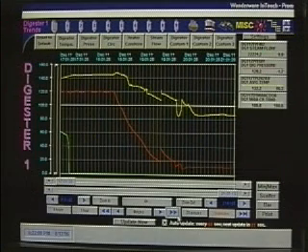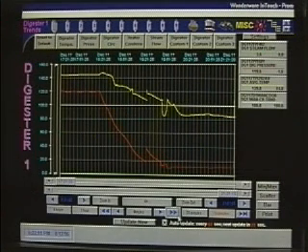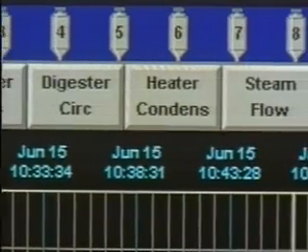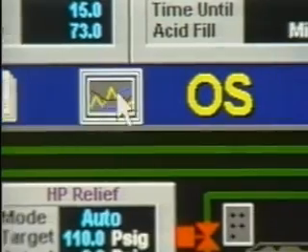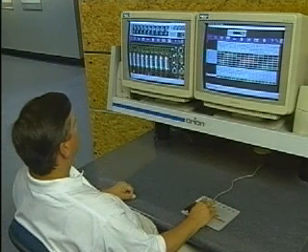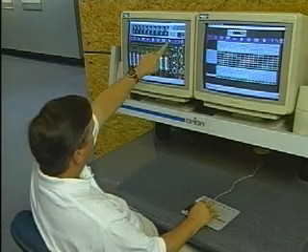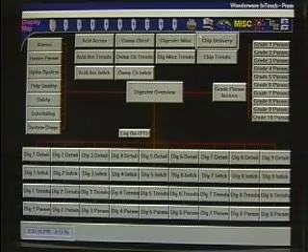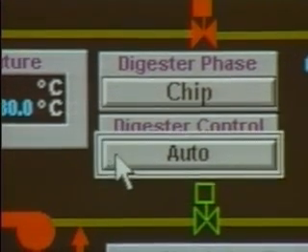The system also has a trends page for digester number 1. Again, these are all context sensitive to where the operator navigates. CyberCook has a link to the optimization systems. We have links to safety access systems, which might be an MSDS server somewhere on the network. We have our help display. We have a tree display that allows the operator to rapidly go to any display in the system for quick access.